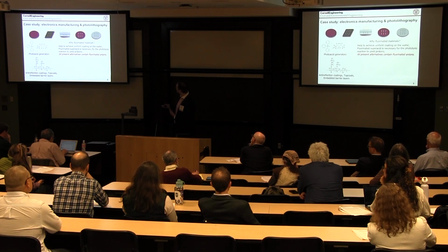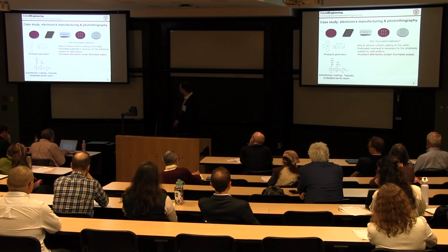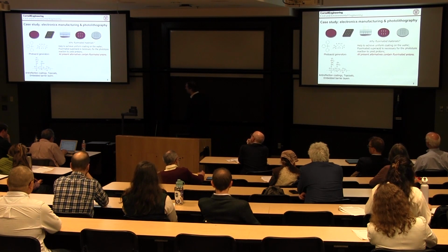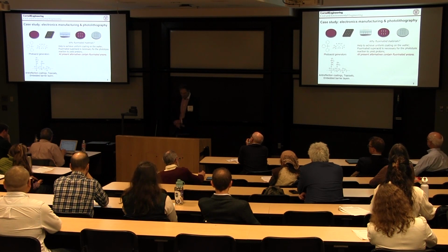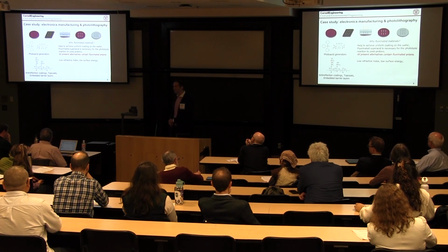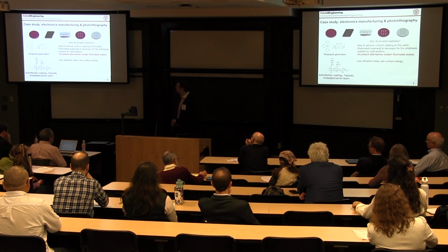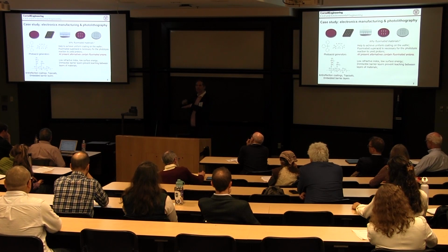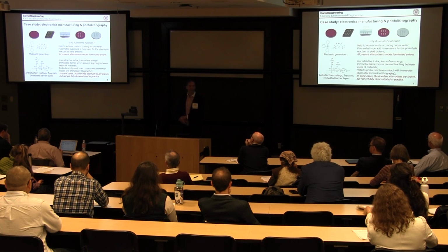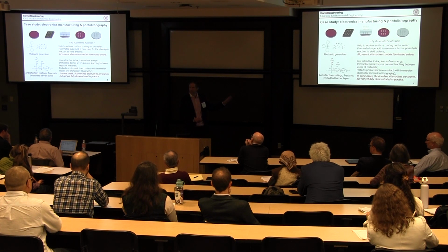Other materials that are often used for enhancing this process in one way or another are fluorinated polymers. You can see there's a side chain fluorinated polymer here. These are things like anti-reflection coatings and top coats. The fluorine atoms in these polymers impart a lot of really important chemical and physical properties, like low refractive index and low surface energy. They help with immiscibility if you're layering things on top of the chip. There are recent studies that demonstrate there are some fluorine-free materials available for these processes, but none of them have been demonstrated in terms of economic viability.